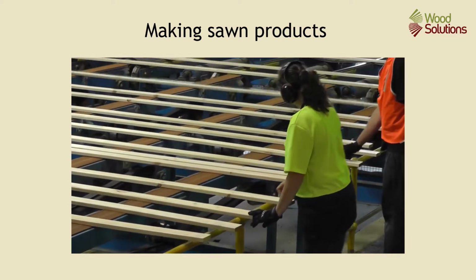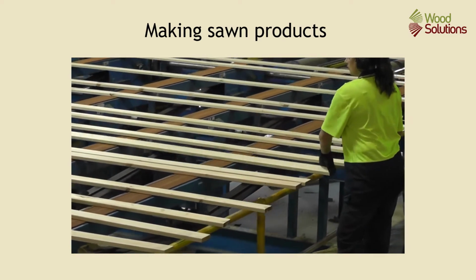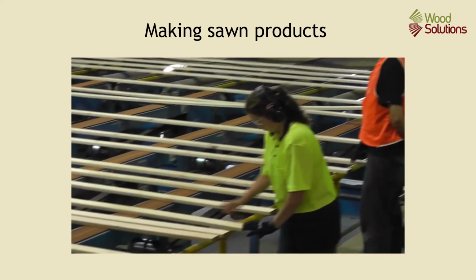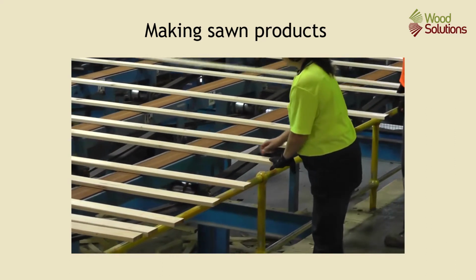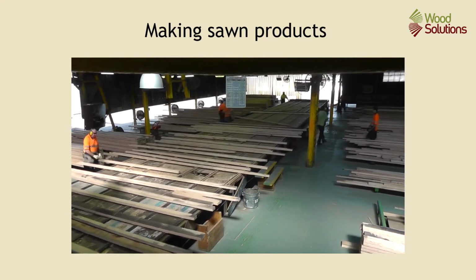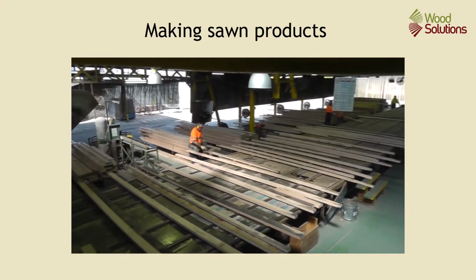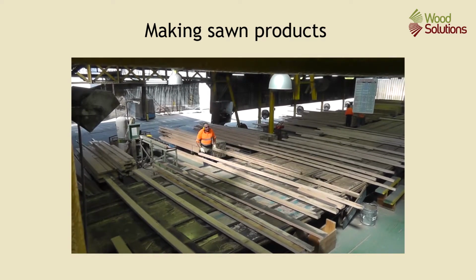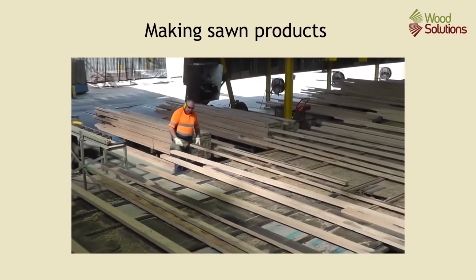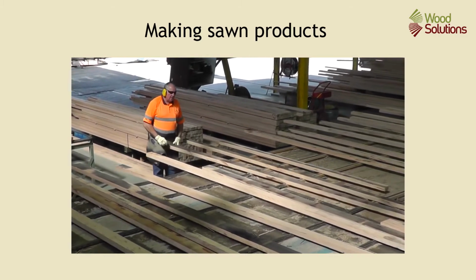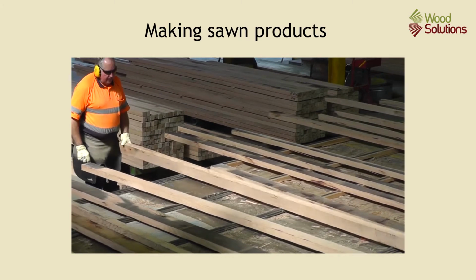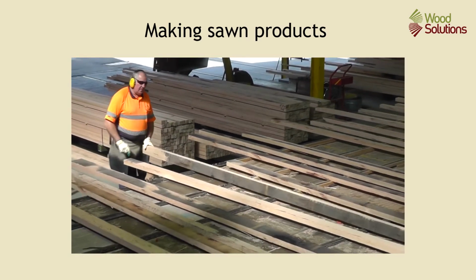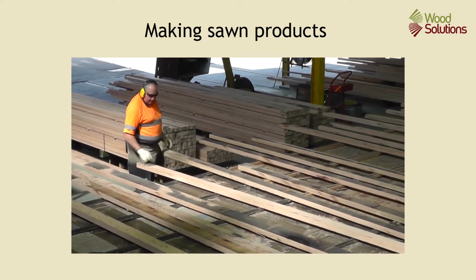Once the timber is dry, the racks of timber are broken down and the boards are graded. Dry milled boards are graded for their intended purpose. Softwood boards are almost always machine graded. This is then followed by an additional visual check. Almost all hardwood boards are visually graded. A trained grader examines each side of the board and assigns a structural or appearance grade to it.